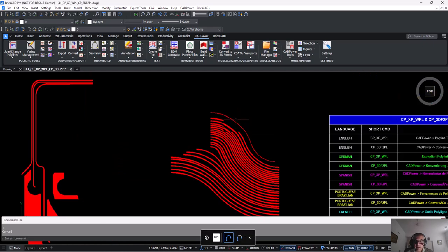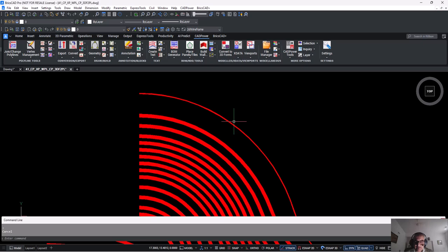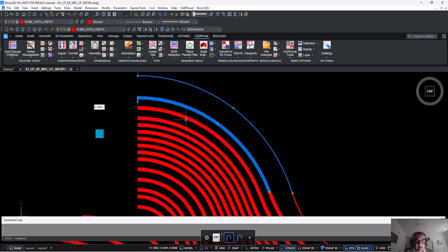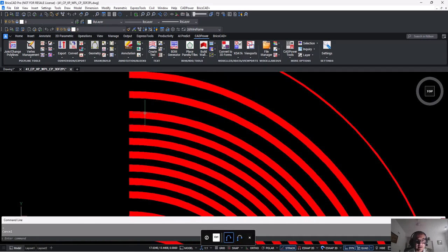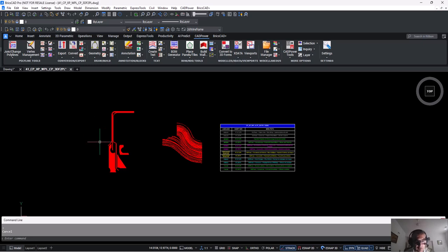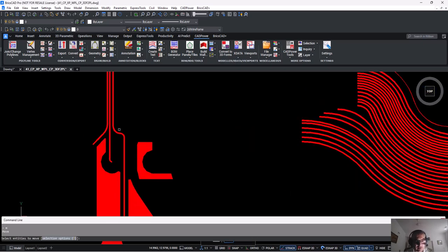I'm happy to present two commands today that will help you in processing polylines with width or solids which need to be converted into outlines. For many practical purposes in fabrication and manufacturing workflows, you sometimes have polylines with width, and you need to convert or explode them in such a way that the width geometry is preserved. We all know that if you explode a polyline with width, the width geometry is lost.